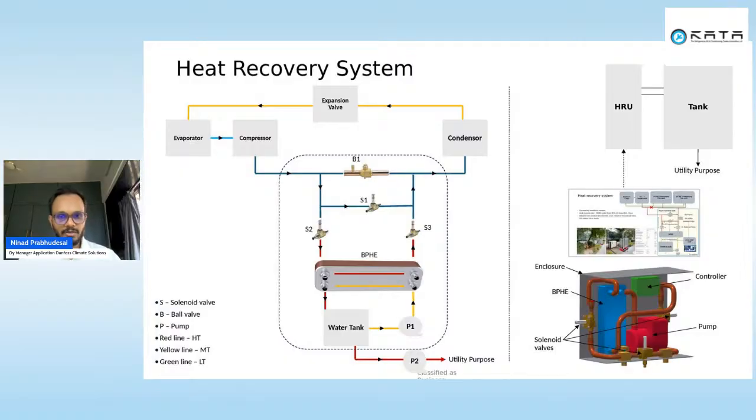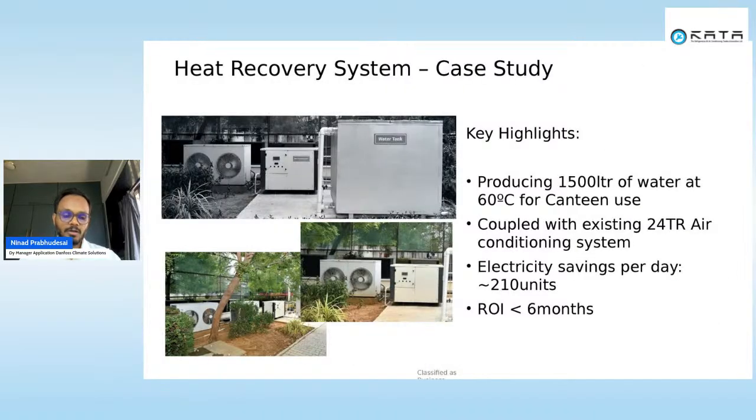We are just diverting the gas to a PHE and using it for heat transfer to heat the water in the tank. There is actually a case study on this, where Danfoss has already installed this in their campus in Chennai. Earlier in the canteen, whenever water up to 60 degrees was required for cleaning the utensils and all, that was being done through the electrical heater.